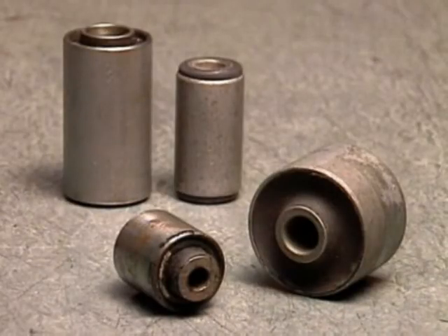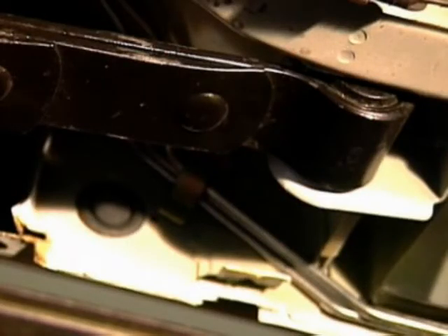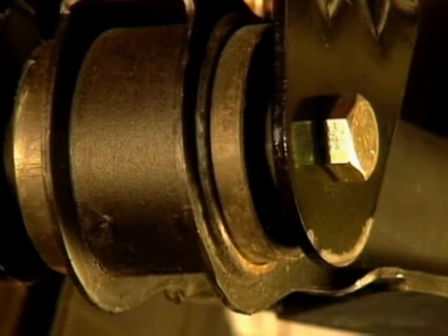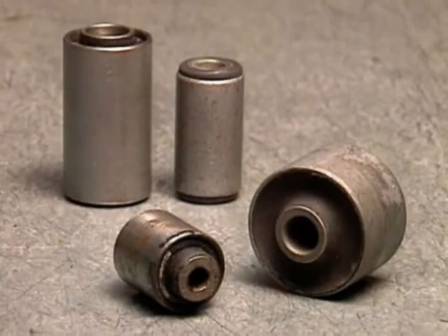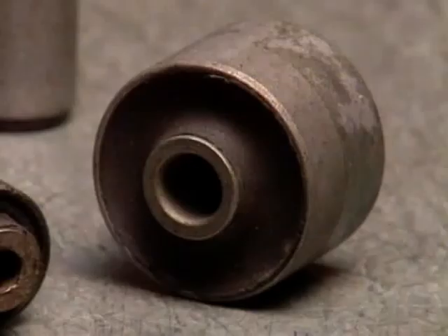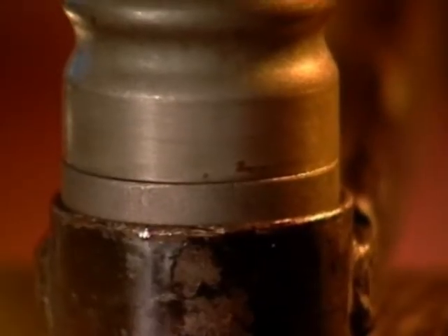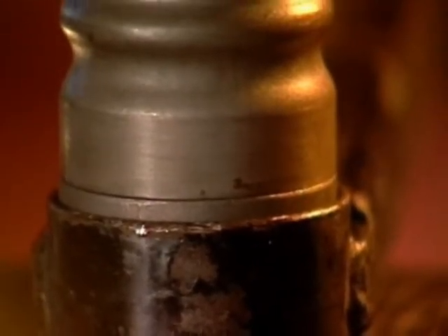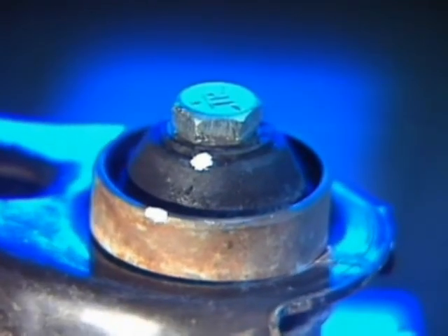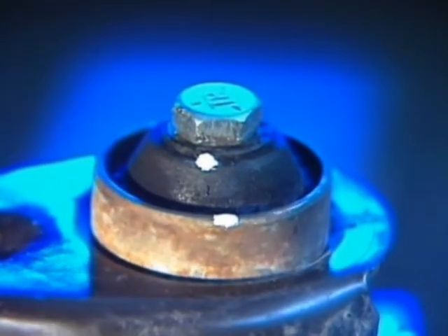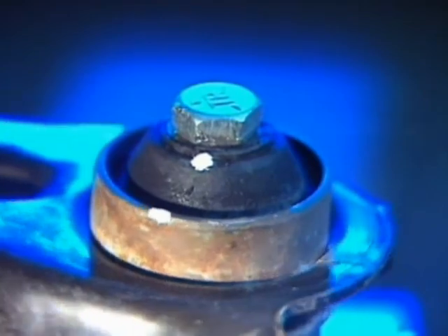Metalastic or rubber-bonded bushings are normally used for the front eye of the spring at the fixed shackle point and also in control arm applications. The bushing has a steel outer casing and inner sleeve. The rubber medium is bonded to both to provide flexibility between them. The outer casing is normally pressed into place in the component. Relative movement between the casing and the inner sleeve causes the rubber to shear without tearing.